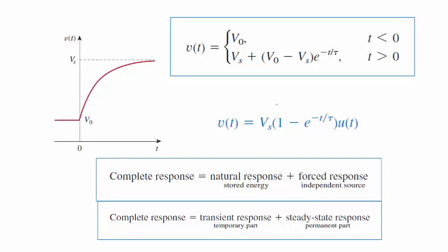So here's a summary of those two complete solutions, whether or not there were initial conditions. So that was a pretty big math derivation. Here's if you had initial charge on the capacitor, and here's if you don't have initial charge in the capacitor. So rather than going through all of that math, there's actually a shortcut way. I sort of alluded to it when I said in a differential equations solution you have a complementary and a particular solution.